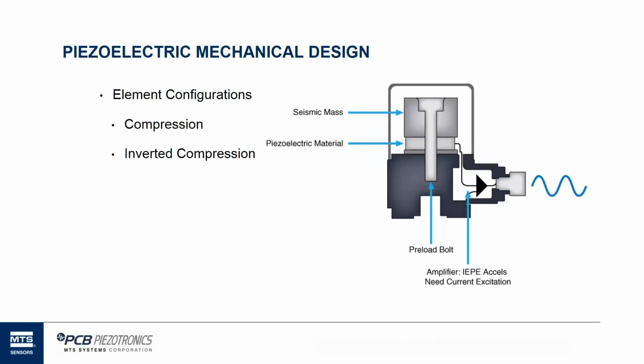That's been used as a very high frequency type design still, but it's a design we've mostly left behind for the most part, because it was used in the beginning because it was a very cost-effective type design. When things were being manufactured on a lathe, that was our lowest cost machine operation. We could make round seismic masses and round piezoelectric crystals, and they all fit together very nicely.